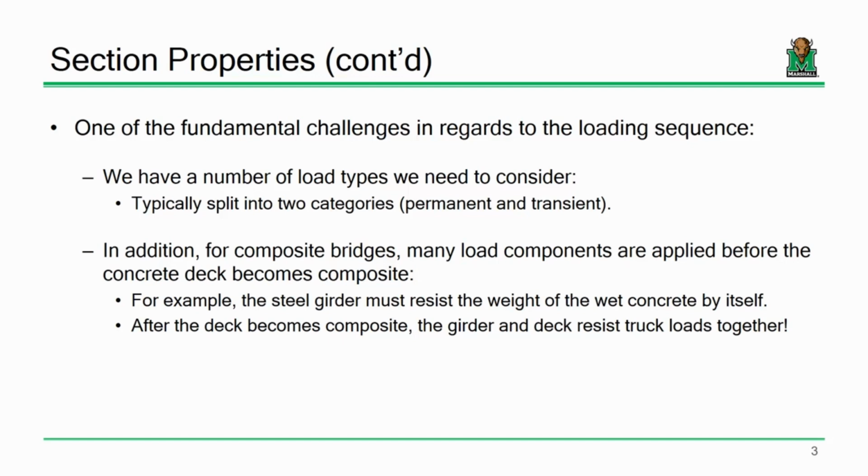that concept of staged construction. So I want you to sort of mentally picture what's going on during a typical bridge construction. So let's say I'm trying to cross a bridge from here to here. Okay, so I've done all my earthwork, done all my grade work and what have you, and I've driven piles or whatever, and capped my abutments, and I'm ready to place my girders.